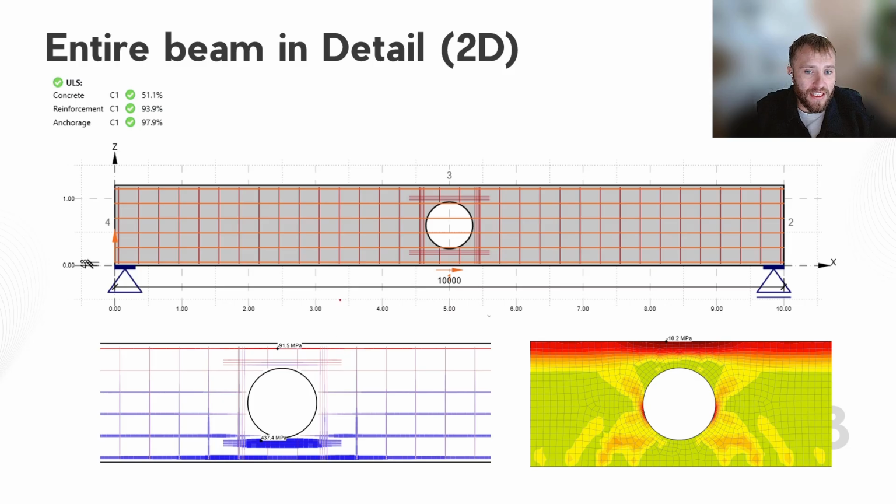Actually, you're able to see that I just reinforced the part, put some opening, and also reinforced the area around the opening to capture the stress concentrations around that. And the most stressed part from the point of view of the tension is the reinforcement close to the bottom part of the opening, 437 megapascal, and under compression minus 91 megapascal for reinforcement bars.